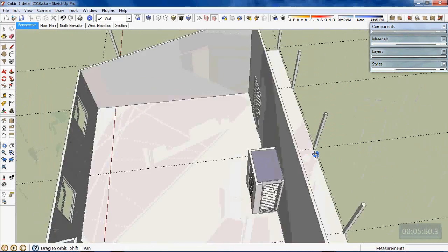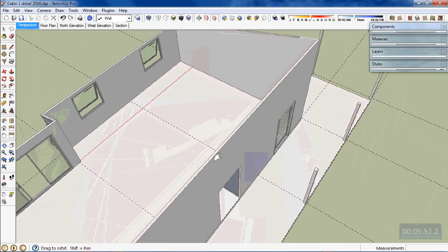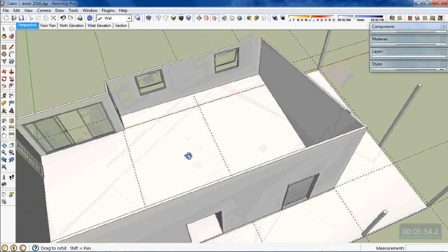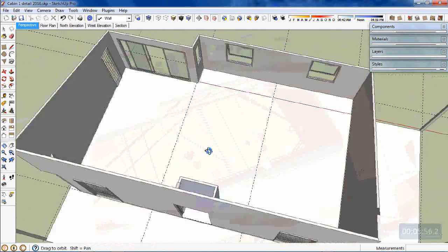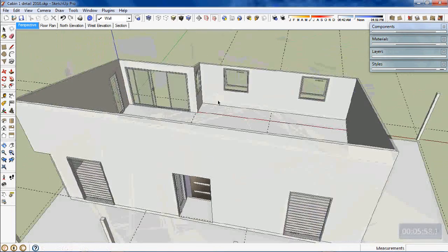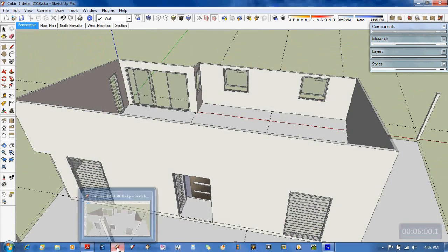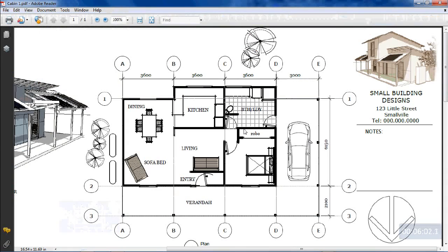So I'm going to now start creating some internal walls, and if I just have a quick look at the sketch handout, here's a copy of the sketch handout here. So basically what we've got is along the 3600 line we can put a wall which basically goes right through, and we'll cut a hole in it for this passageway through here. But we'll draw a wall initially maybe straight along that line, and I'll show you where I'll head to with all of this. So back to SketchUp.